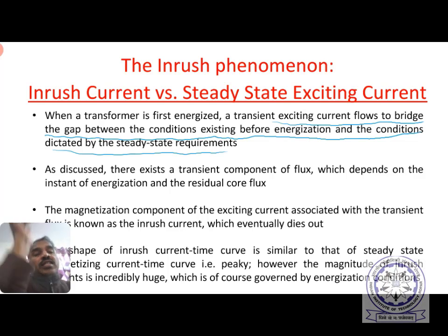Don't go by like that. So it is related to energy actually. At that instant, if you switch on, there will be no problem. What that instant is, we will see soon. But if you disturb, means if you are switching at a different position, then some transient will arise within the system, which will adjust the system to steady state, and until then the transient will last. Of course, the transient is associated with some losses which will eventually make it die. So this is how the response will be.